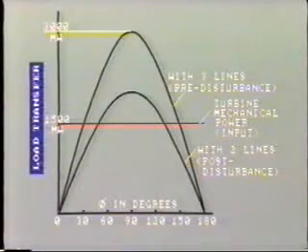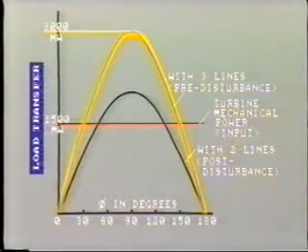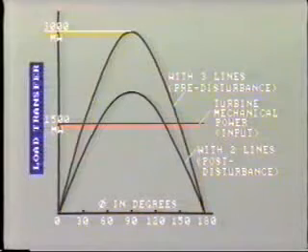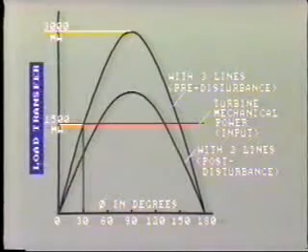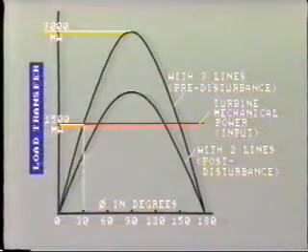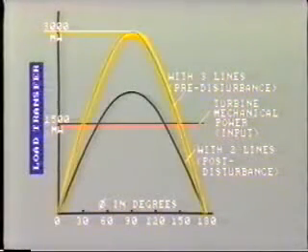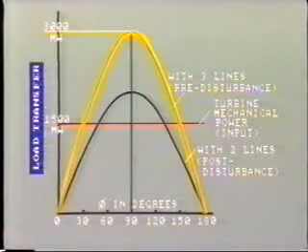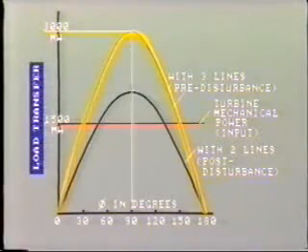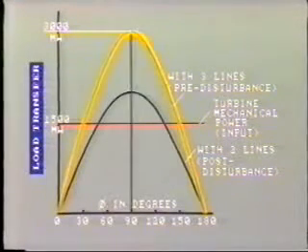The power angle between the two buses is shown by this curve. With 3 lines in service and a total load transfer of 1,500 megawatts, the load angle here is about 30 degrees. You can see that with 3 lines in service, we could actually transfer more power. At a power angle of 90 degrees, the capacity of the transmission circuit is about 3,000 megawatts.